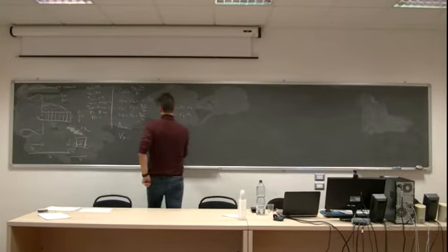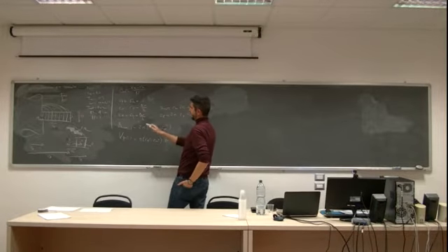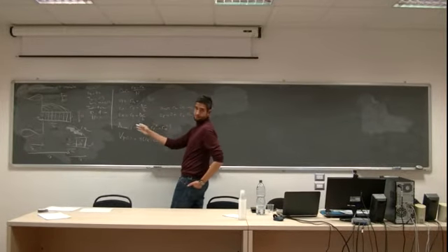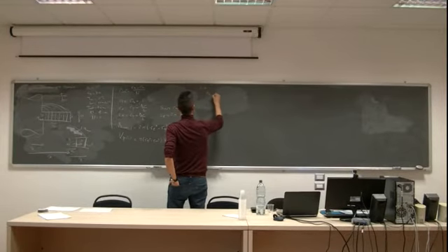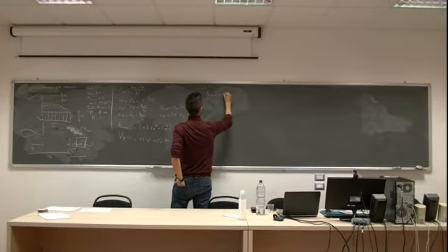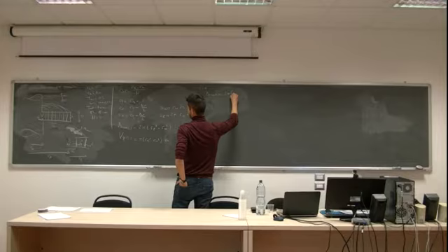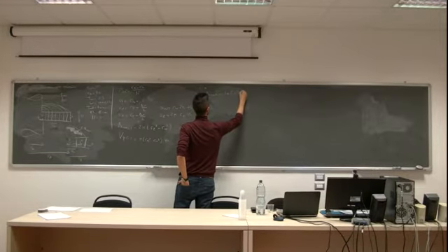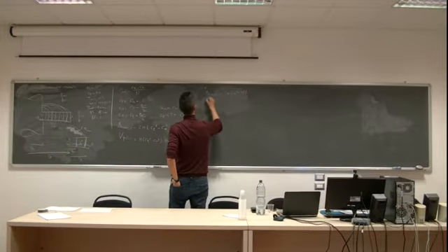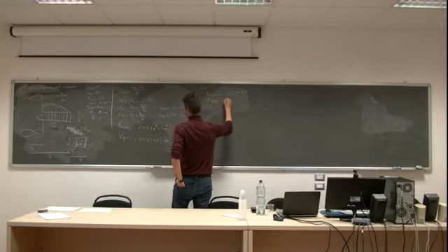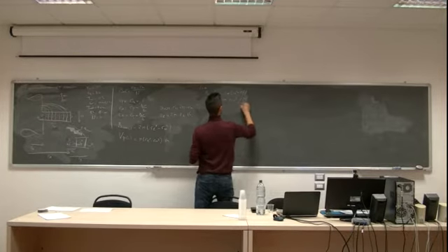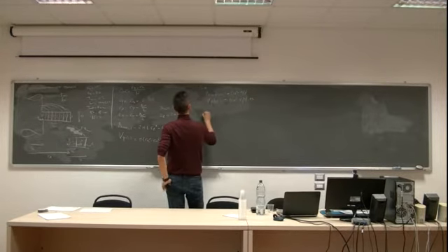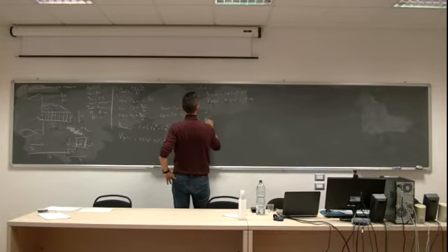This has an exception, so this is valid from i equal to 1 to i equal to 6. If i is equal to 0, the convection area is 2 pi r_e minus r_p, and the volume of 0 is different, because the first node doesn't have any west node. And for i equal to n, the same but in the east.